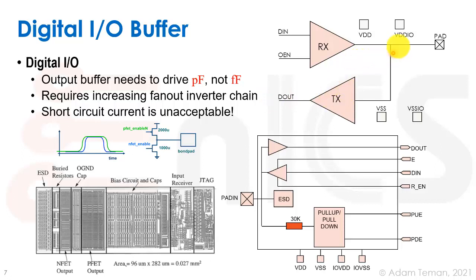Okay, and so what we would have over here is an output enable on this guy. So when output is enabled, then this is a driver, and it's going to be driving the pad, and this is configured to be an output. At the same time, we're also tapping this, but it goes into a capacitive input, so it doesn't bother us that we're driving this out. But if we want this to be an input, and therefore the drive is coming from outside the chip, we disable the output enable, and this becomes high Z. And if it's high Z, then we can drive in things from the external world. So this becomes an I/O buffer.